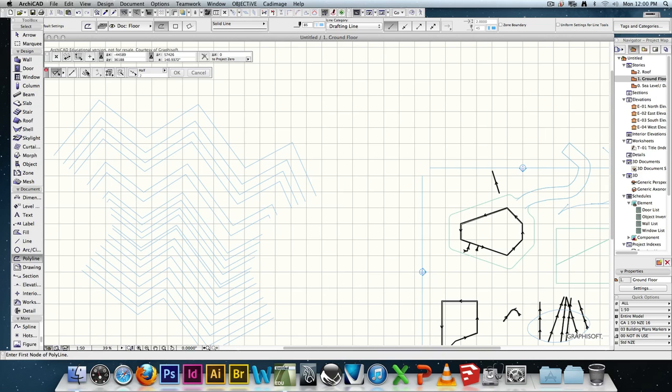On Wednesday morning's tutorial, we're going to be working on the assignment a little bit closer. Just remember, this session's always just about ArchiCAD and learning new things. What we're going to do is bring in our site plan, that A4 one that I gave you. We're going to drop it down, scale that image, and then start drawing contours onto it, and then create a mesh out of those contours using the magic wand.